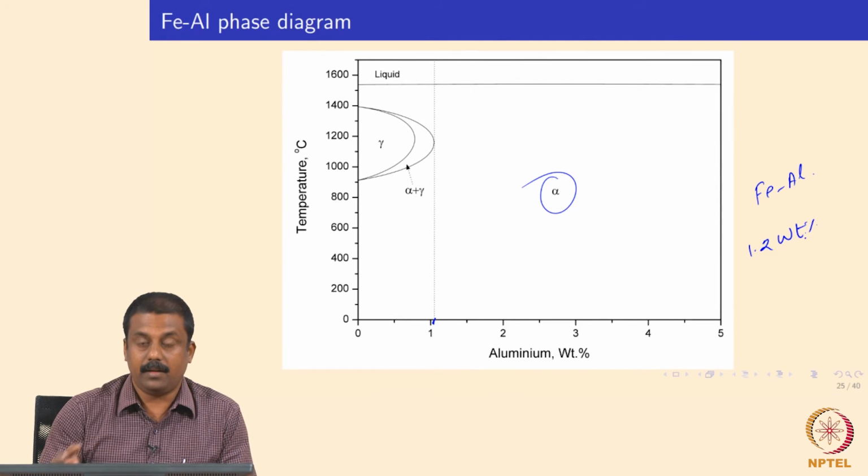And this effect is not seen in silicon based strip steel because silicon is not that effective in stabilizing ferrite or even in stabilizing other microstructural phases, and because of the very strong affinity of aluminum for delta ferrite, beyond say 1.2% aluminum, if present in delta ferrite, the delta ferrite gets stabilized and then it cannot transform to austenite in subsequent cooling.